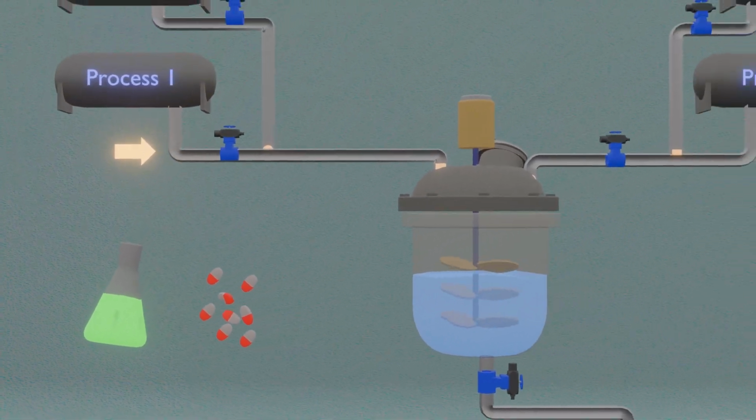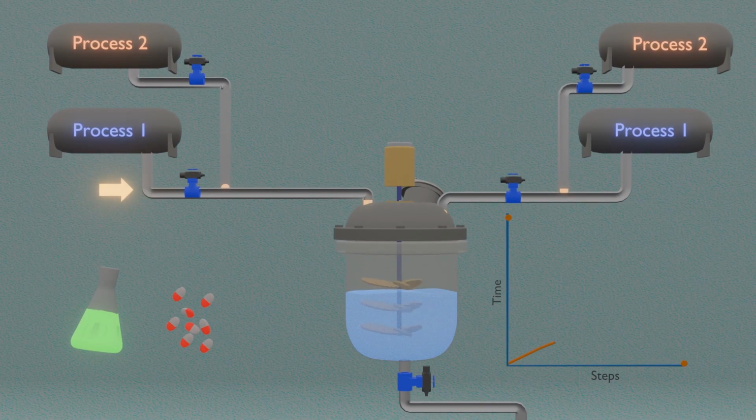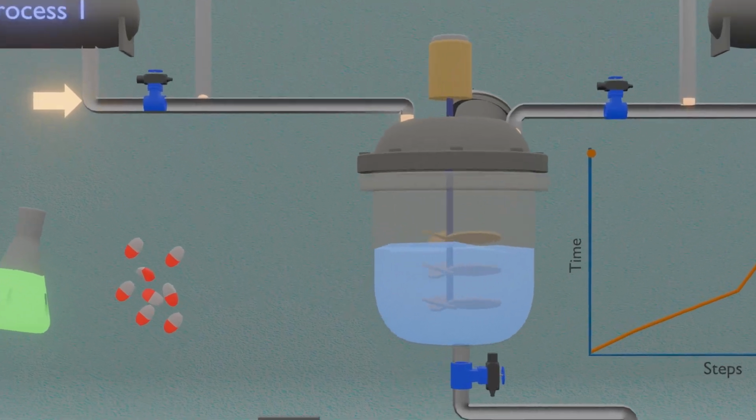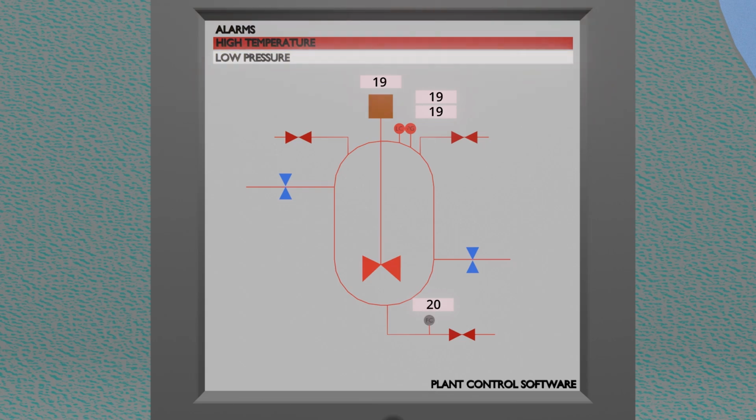The disadvantage of a batch reactor is time, as you have to charge, react, discharge, clean and then recharge, all of which takes time where you're not producing any product. For large-scale, high-volume production, that dead time between batches makes the batch reactor far less efficient than a continuous process. It also means more manual intervention and tighter operator oversight, as somebody has to charge, react, clean every time.